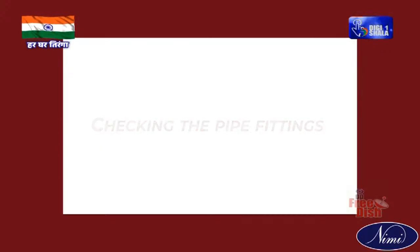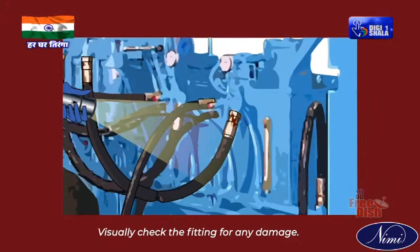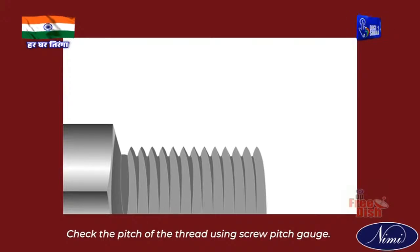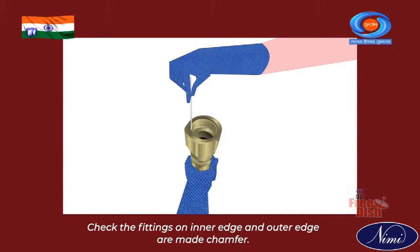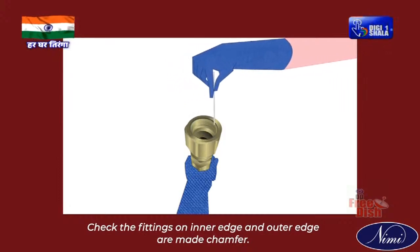Checking the pipe fittings. Visually check the fitting for any damage. Check the pitch of the thread using a screw pitch gauge. Check that the fittings on the inner edge and outer edge are made chamfer.